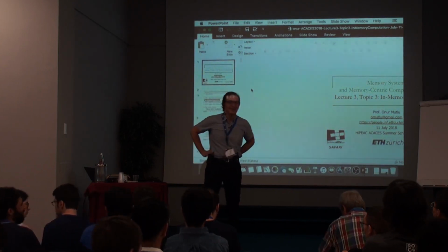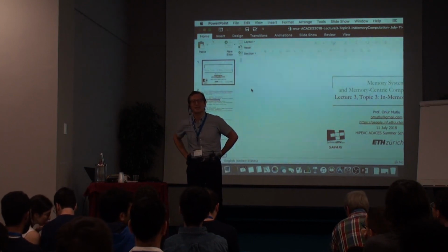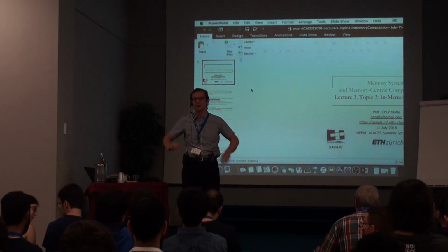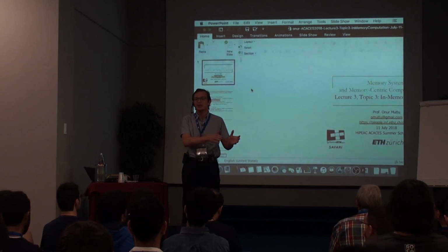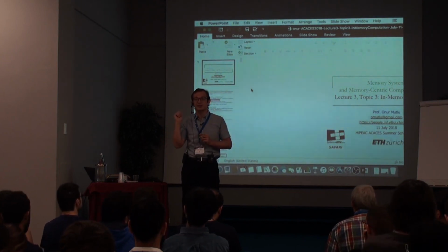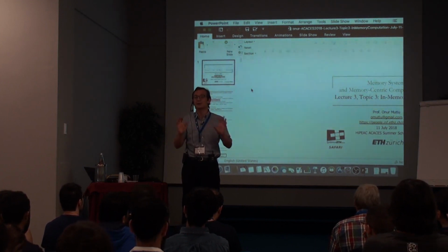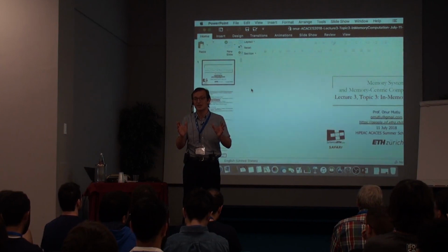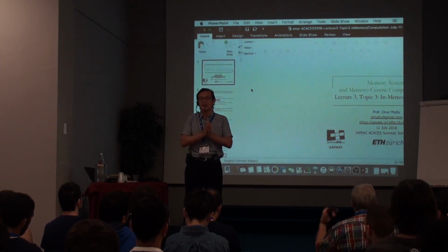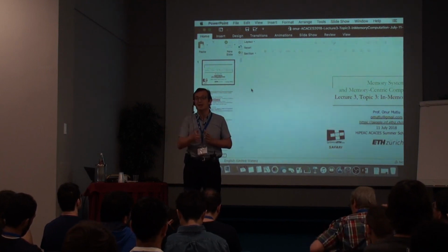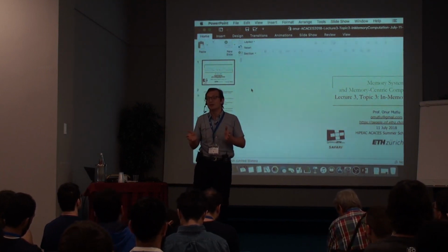I think there are two answers to this. One is, it's not easy. You could do circuit simulation, but this is really, really hard to simulate. And all of this electromagnetic coupling, I think we don't have very good models for that sort of simulation. So I think that is very difficult. But you could say, why didn't they test memory using all of this hammering? That increases the test cost a lot, actually.